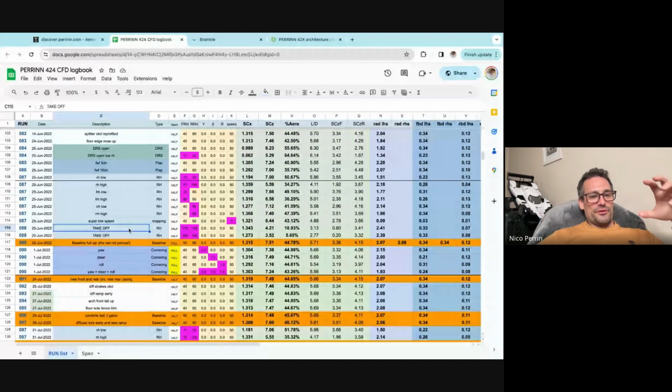And we've got what we call takeoff tests as well, where the ride height is extremely high, 115 mil, because we had situations where the front of the car, the tires were losing contact with the ground at the Nürburgring, and the downforce turns into lift at the front, and the car starts to take off. So we had to look at this in CFD very closely. And we've applied some speed limiters around the Nürburgring to counteract this problem.